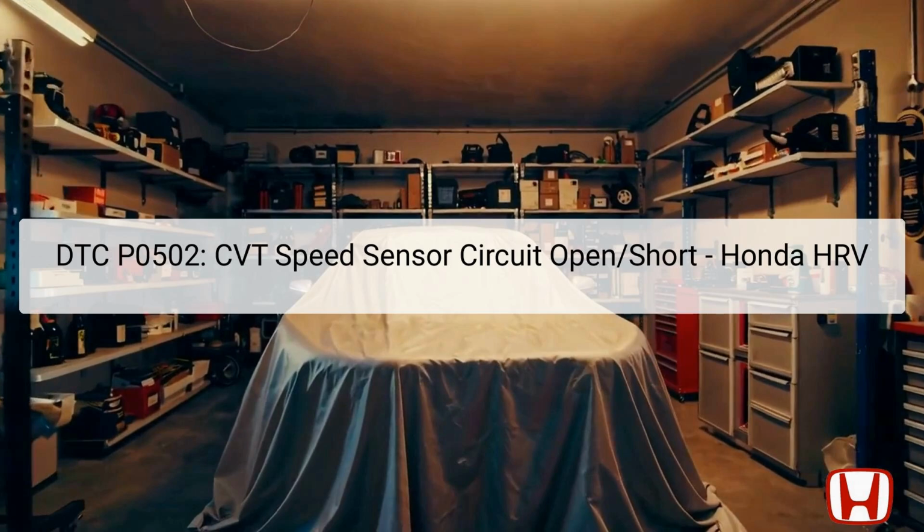The DTC P0502 indicates a problem within the continuous variable transmission CVT speed sensor circuit, specifically an open or short condition. This sensor plays a critical role in monitoring the speed of the transmission, sending vital information to the powertrain control module PCM for proper vehicle operation.